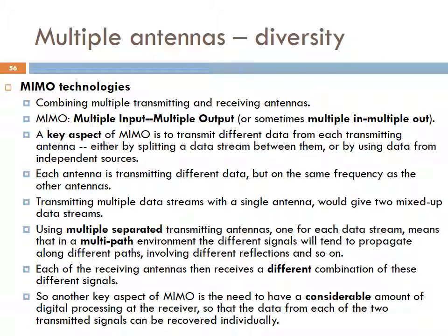This is done either by splitting a data stream between them or by using data from independent sources. Each antenna is transmitting different data but on the same frequency channel as the other antenna. So using the same channel, we are trying to send more data. So we are increasing the capacity of data transmission using the same frequency channel.